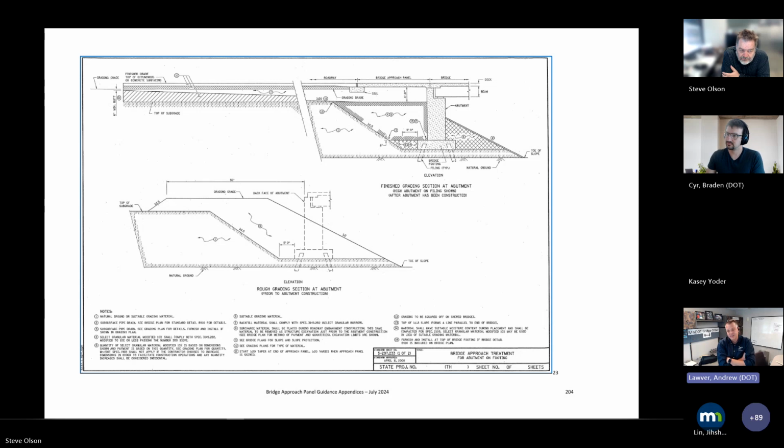The main reason is not anything that the fabric does, but it makes the contractor put in the backfill at the specific layers. They're not able to just have the inspector go to lunch and then fill in the back of the abutment and be done. They need to do each layer, and that makes them take the time and compact each layer.